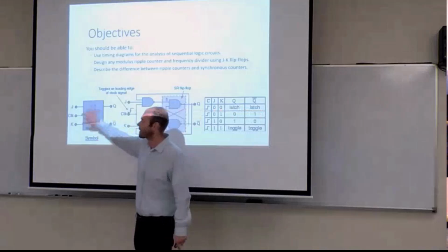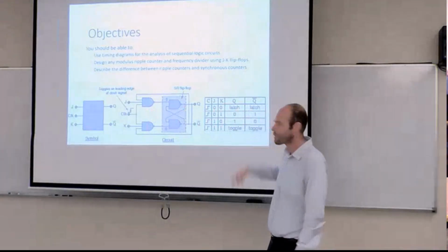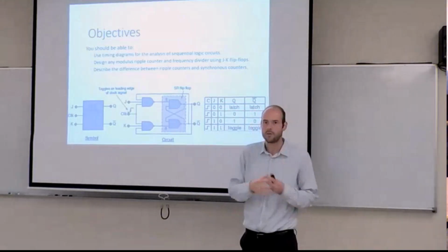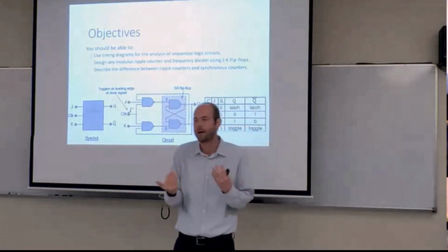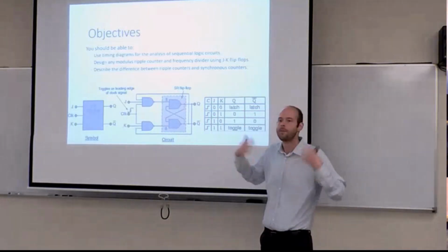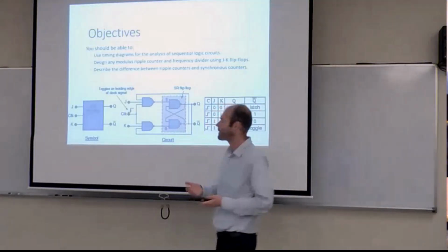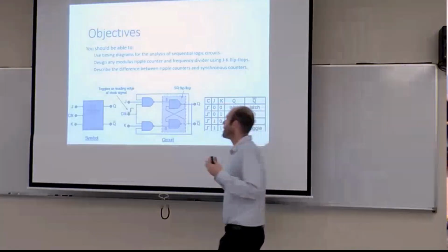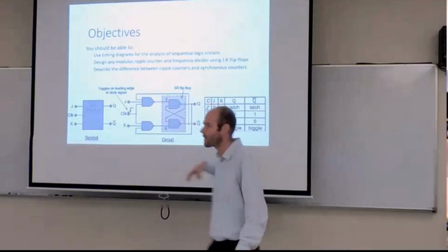So our main working unit here will be the JK flip-flop for building out counters and a lot of future devices. We're going to have some sections on registers, which is where you can queue up bits to be sent over a serial port or to convert them from serial to parallel forms of transmission. Set up the registers that are maybe holding information before they're fed into your CPU if you're talking about a PC. So the holding and manipulation of banks of ones and zeros is all built on the backs of the JK flip-flop. And so we did build out all our logic gates.